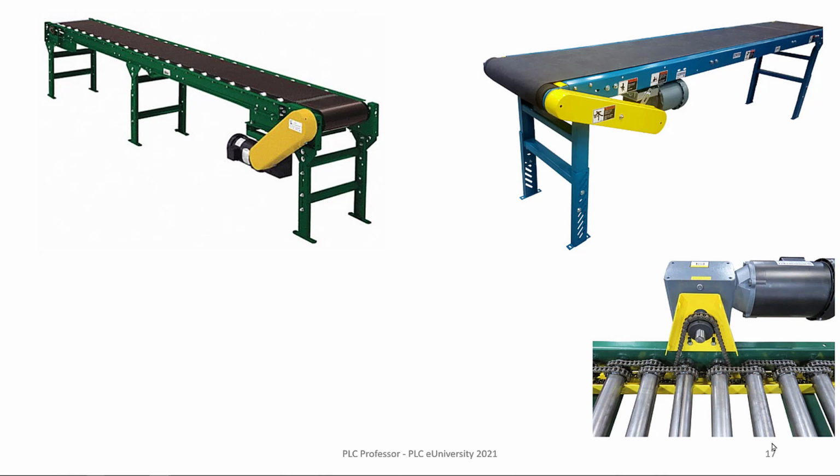And the product or the cartons move along these rollers because they're all driven by the electric motor. And you can see how it's configured with sprockets and chains. Now, the difference between the motorized rollers and the belt conveyor is that some things can slip easier on the metal rollers than they will on that rubber belt. Also, the shape is not as important on the belt as it is on the rollers. You don't want the parts kind of tipping down between the rollers.